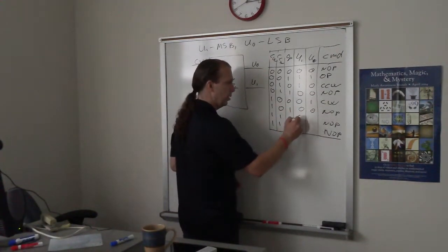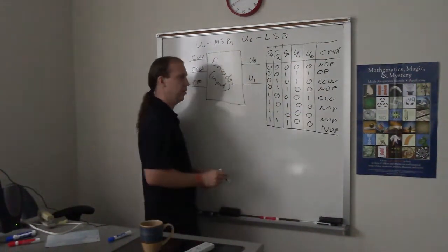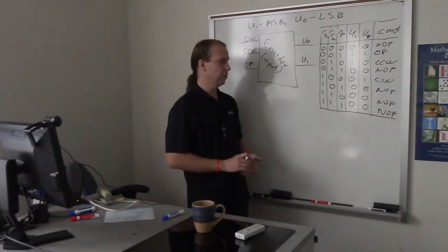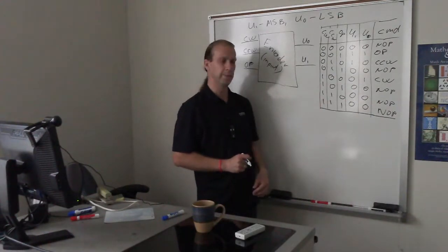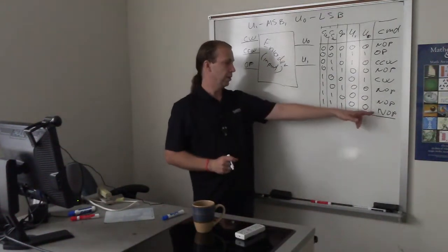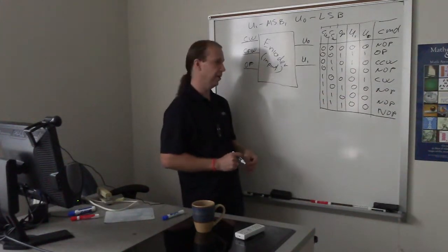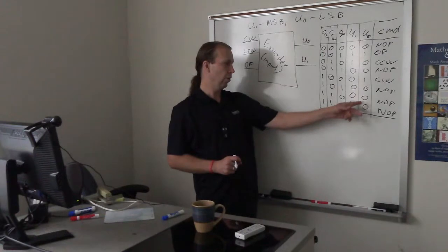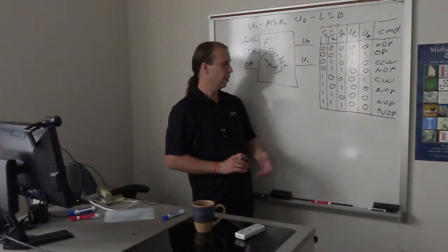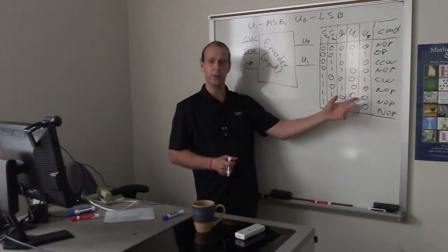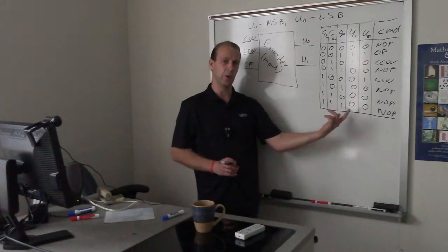And actually there is one observation, one idea, which I used without explaining it to you yet. The no operation command is the one which is most frequently used. Encoding it with 0, 0 looks like a good idea just because we want to stay with minimal energy in the state which is most likely to happen.